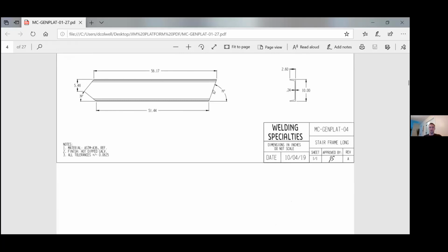If you do over constrain a drawing by putting all those things on there, I think, for example, one of these, top or bottom, should probably say reference, because by the time you've dimensioned out the top and that angle and this height and this angle, this should come out in the geometry, if that makes sense. So this may actually be over constrained. Be careful with that. If you really want to have it on there because you think it's something that's going to be useful to measure, then just put that as a reference dimension. Or just don't put it on there at all.